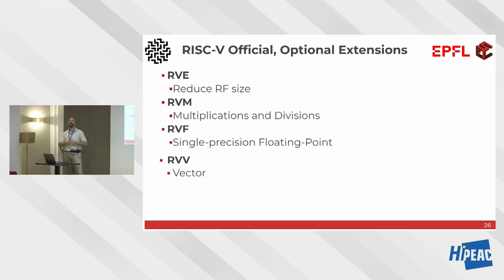So a program compiled with RV32I, for example, the integer, Boolean and arithmetic operations for RISC-V, can run on every RISC-V core. Do you agree? Because they all implement the same spec. So if you compile your application with the flag RV32I on your compiler, and your processors are compatible with that, they work. Custom extensions mean I'm customizing the CPU, which means that my code compiled for my custom extensions doesn't run on your core, which doesn't implement those custom extensions. That's the main difference.